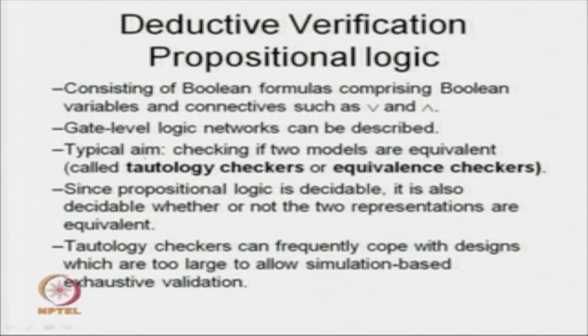In case of deductive verification, what we basically check is whether two models are equivalent or not. We call these tautology checkers, because in our design phase we have an abstraction. First we come up with a model, then we make it more refined, and we go for another level. Every time we have to check whether we are going to get an equivalent translation or not. So, we can look for such an equivalence checker. Sometimes you can say tautology checkers or equivalence checkers.